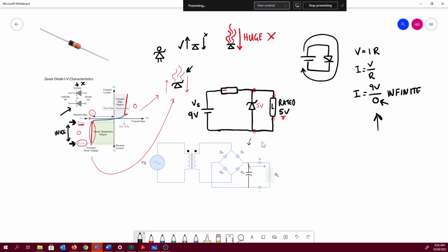Beautiful. So you chuck a capacitor across like this, and that's going to do the thing that capacitors do. When the voltage is increasing, that's going to charge the capacitor, and when the voltage is decreasing, the capacitor is going to discharge, and that is going to turn this really lumpy signal into something that looks a little bit more like this. Ripple, ripple, ripple. You'd have 3 ripples, right? Anyway, cool. But the point is, this has still got a bit of a ripple, which we don't like.